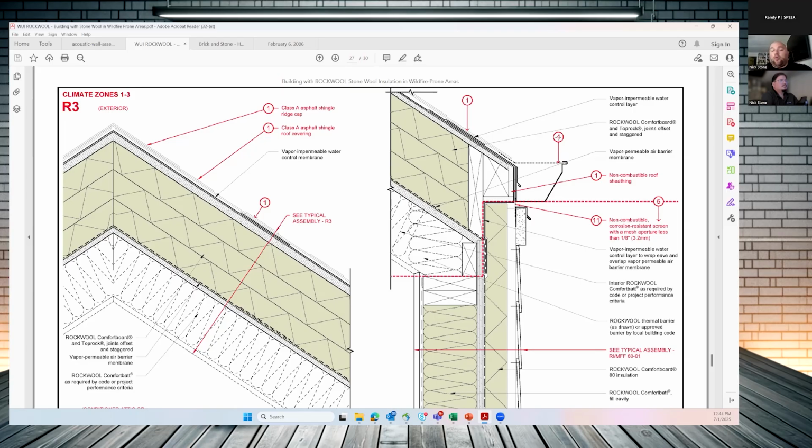But in your normal areas, your bedrooms, things like that, you're going to find it's a pretty similar process. If your wire is 18 inches off the ground, making up numbers, you bring a full batt back to the top of that, pull it up, and just cut 18-inch blocks and slide them in underneath the bottom.